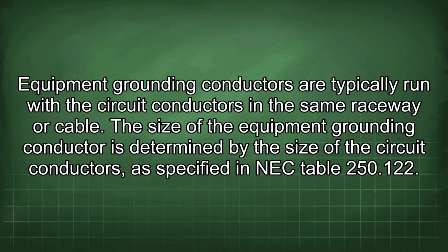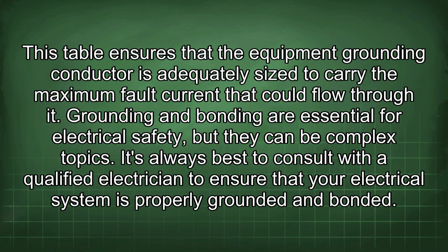The size of the equipment grounding conductor is determined by the size of the circuit conductors, as specified in NEC Table 250.122. This table ensures that the equipment grounding conductor is adequately sized to carry the maximum fault current that could flow through it.